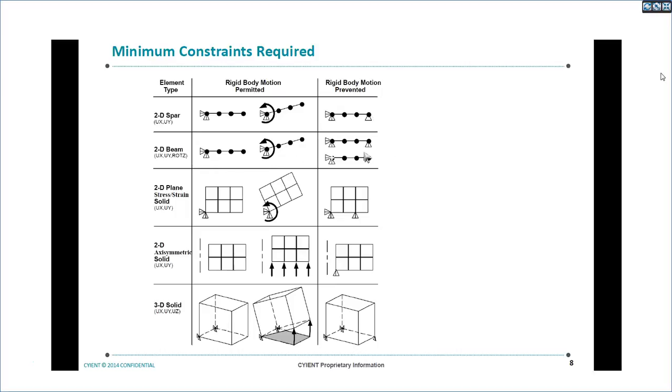Similarly, the same is the case with the beam as well. In a beam, there are two ways you can apply constraints, depending upon our loading pattern and simulation beam representation. These boundary conditions will definitely allow rigid body motion, but here there are two conditions. One is the cantilever condition, another is the simply supported condition.